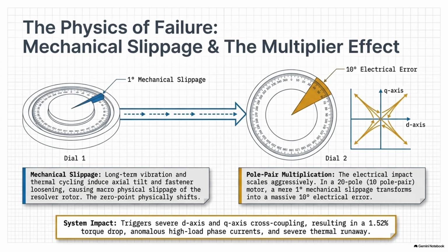Exactly. See, this is what I find so wild about modern engineering. You can have a motor block bolted together to the millimeter, torqued to absolute perfection, physically indestructible. But a simple software flash version mismatch can cause the entire physical control logic to collapse at highway speeds. It collapses because the controller is completely blind without its calibration file.